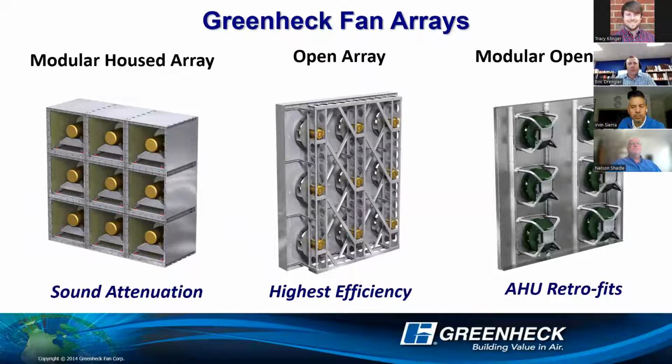So we've got housed arrays, there's open array and a modular array. Open array works very well for built up systems where there's ability to use a crane to put this in place. Maybe there's a situation where it's a built up air handler and labor is a concern. This particular one can be craned into place and then built around it. Or if it's a retrofit application, this would not work very well because obviously you've got to break it down and get it down into a basement or up into maybe a penthouse. That's where more of a modular version of a fan array would work better because all these pieces can be broken down into pieces that can be carried in through doors.